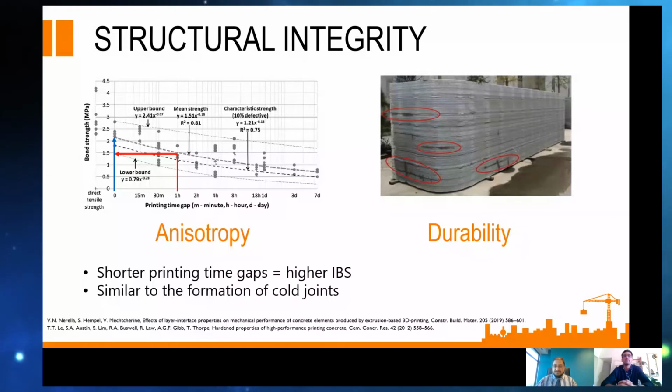We have quite a lot of binder that we use, very low water to cement ratios, 0.45, which then gives quite a lot of strength to the material. So you can keep higher strengths and bigger strengths. Absolutely. However, we appreciate the fact that you don't necessarily always want unnecessarily strong concrete. You know, it should be pragmatic. It should have an intended application. So you can then design mixtures for a certain target strength, as I previously mentioned.